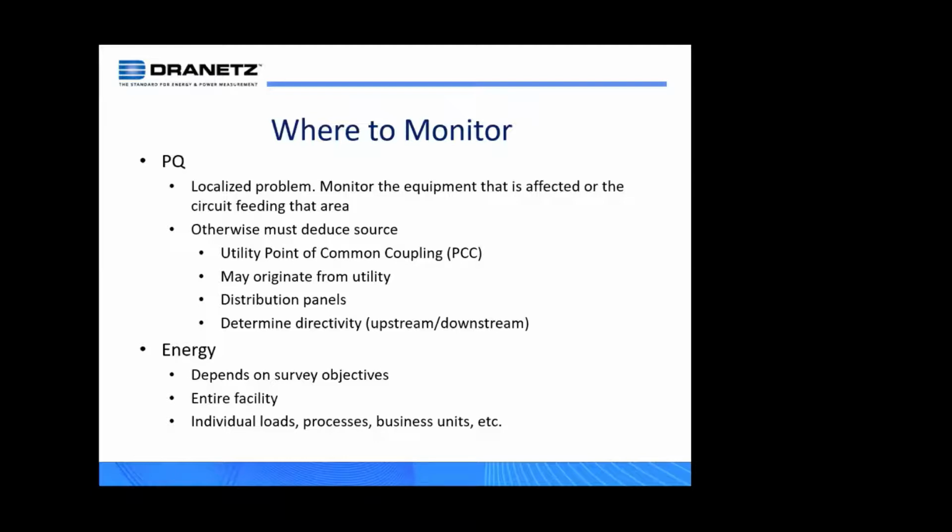And then energy, it really depends on the survey objectives. Generally, you're monitoring the entire facility. So you're going to connect the meter at the point of common coupling, or you're going to connect the meter to each feed, because there are facilities that might have more than one feed. So obviously you're going to have monitoring at each of those feeds, and then in post-analysis, you basically aggregate all the readings together to get a total reading.